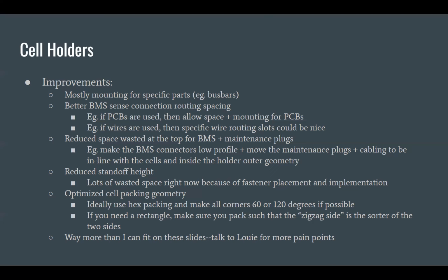And then we looked through and realized this is going to take forever to manufacture. And every time we rip it in and out, the chances of us clipping these wires and ripping stuff off is super high. So we said, rather than have wires, let's make PCBs that do the wiring for you, because those are rigid and you can epoxy them to the cells. And it's like this whole thing.